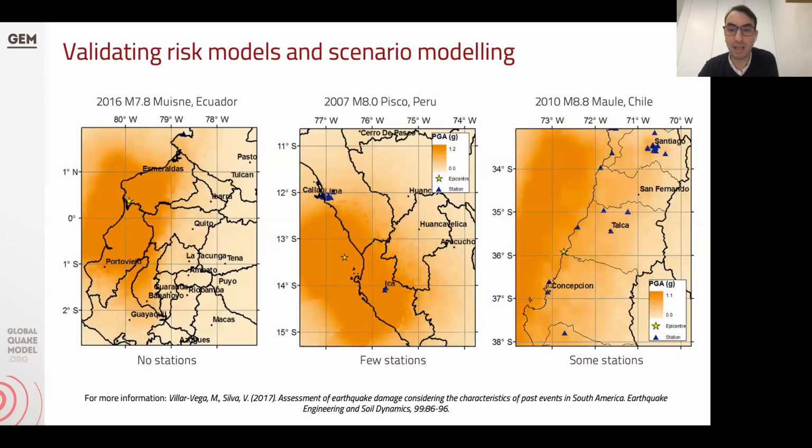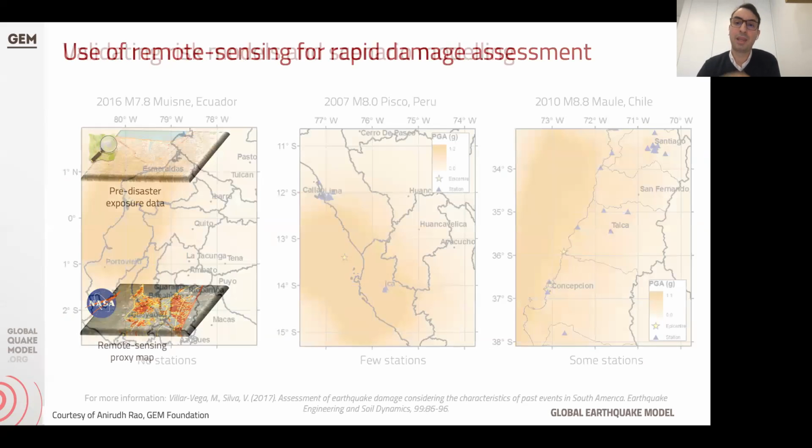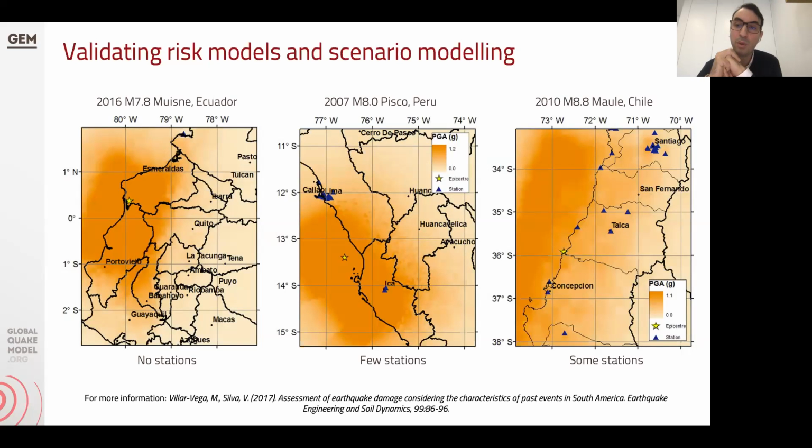Okay, you might also have heard about the ShakeMaps from the USGS, which is probably one of the best sources of information for ground shaking after events. You can also see that a lot of times they do try to incorporate data from recording stations, but sometimes, despite the fact that the data exists, it's just not available for us to constrain the ground shaking. So because of that, in my opinion, in order for us to improve how we estimate the losses from past events, there's a lot of work that still needs to be done on the ground shaking estimation side. And I feel like the physics-based model is probably a way for us to reduce a little bit the uncertainty that we have there.